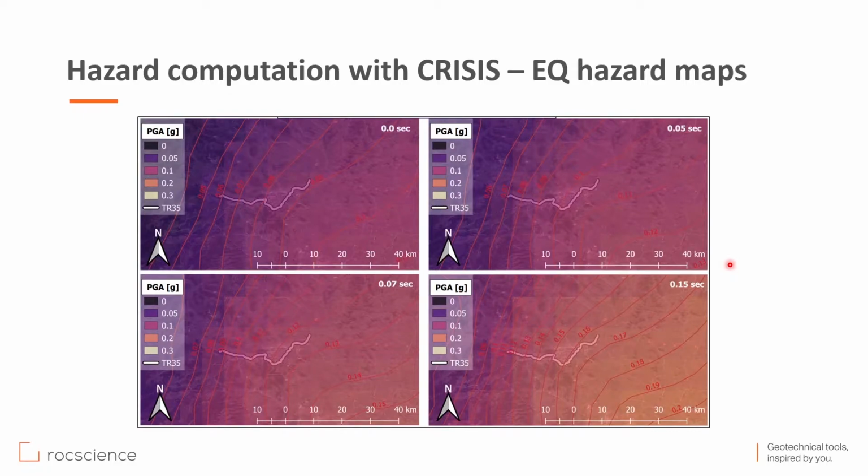However, as a result of the study carried out in the framework of this project, the bedrock peak ground acceleration and the response spectrum were calculated for entire Cluj-Napoca area, which were summarized in a map appendix, which maps were prepared by using QGIS. So we have selected the response time periods required for the construction of the design spectrum for future design work in accordance with the requirements of both Eurocode 8 and the Romanian regulations.